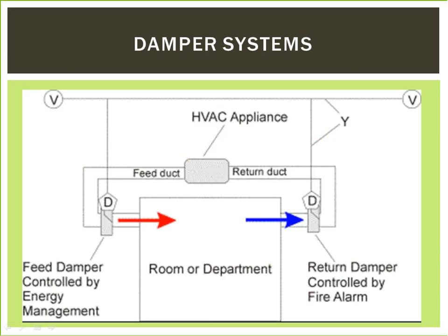A damper is a valve or plate that stops or regulates the flow of air inside a duct, VAV box, air handler, or other air handling equipment. A damper may be used to regulate cooling or heating for room-by-room temperature and climate control. Its operation can be manual or automatic. Manual dampers are turned by a handle on the outside of a duct.